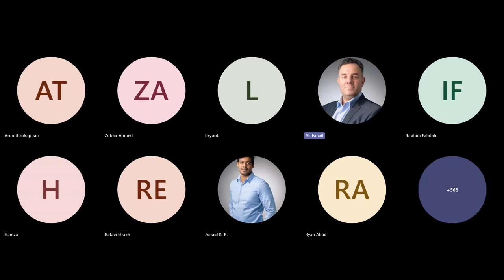For modeling walls, I think at the moment it is not necessary to have all finishing layers, because we are not checking any regulations related to the finishing layers. And we prefer to have the BIM model not very big for no reason or for no added value. But if your model is already modeled with finishing layers, of course, it does no harm if you stay within the maximum limit of the file size.